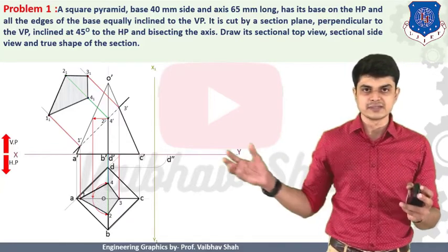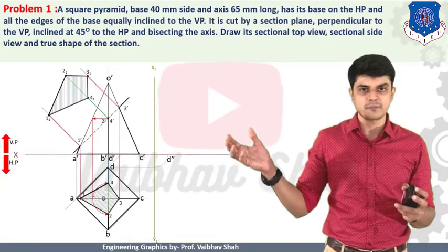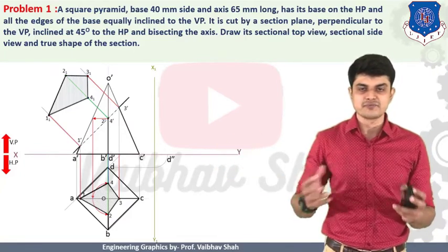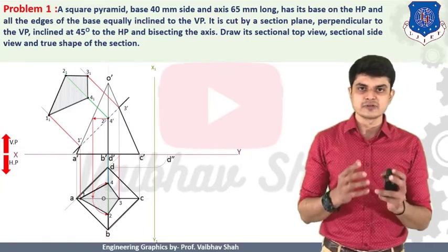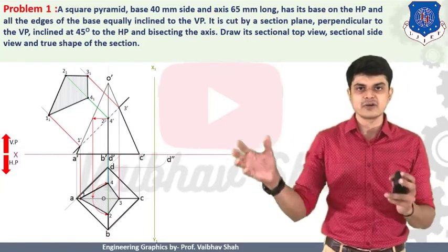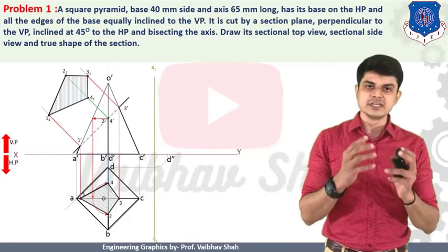So we know that on this arc your point is your point D, and on the horizontal line from your front view you will have point D dash coming. So the intersection of the horizontal line of D dash and the arc of your point D will give you D double dash.